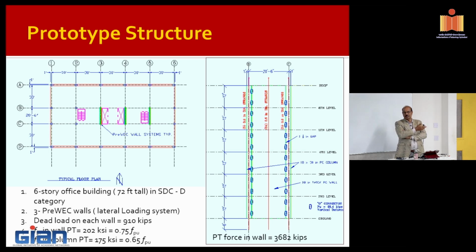If it's cast in place, the damping, the stiffness, everything is determined by the time you determine the amount of bars that you need in the base of the column, for example. That was the misconception, because everybody initially, even with a tuned mass damper or base isolation, said, okay, we need to come up with 20% damping, 25% damping, because that's what the cast in place are doing. But that's not a good reference to start with, is what I'm saying.